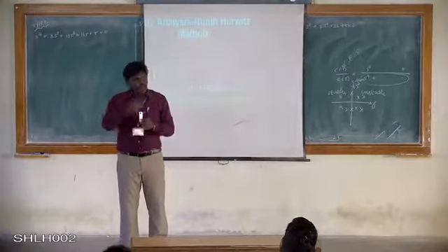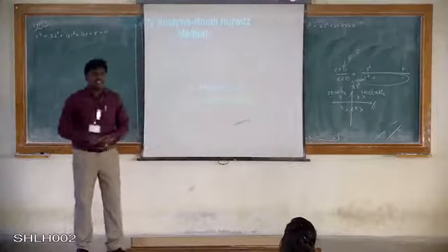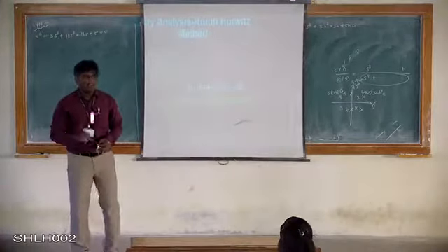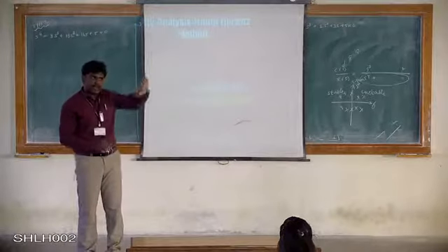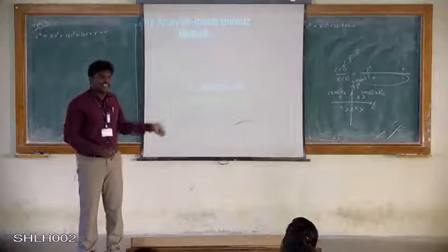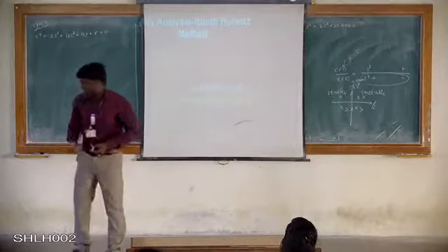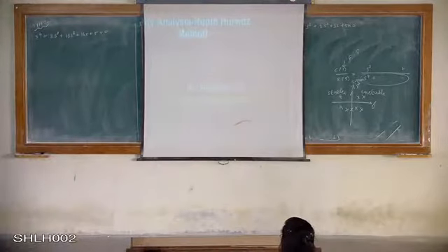So instead of doing that plotting, we use the Routh method for analyzing, right? We will have to make the Routh table, and by seeing the Routh table, we will have to tell whether the system is stable or not. Okay. Now, we will see some of the roots.